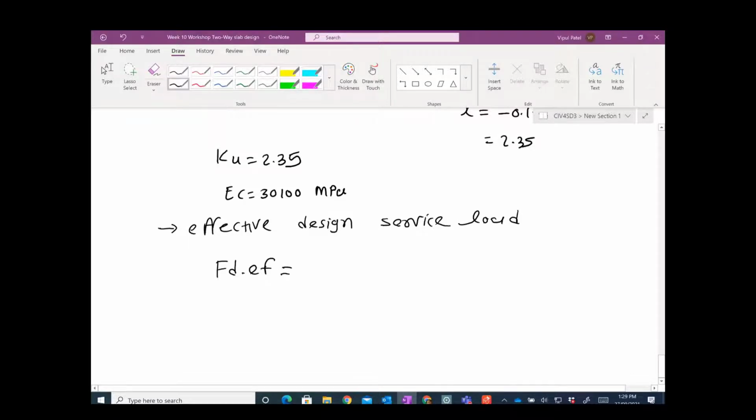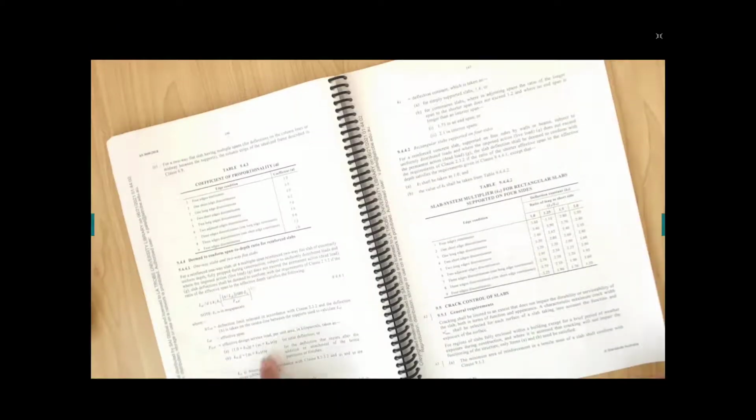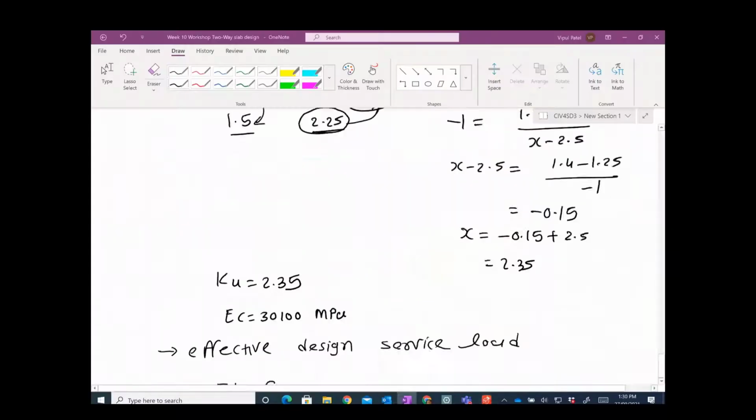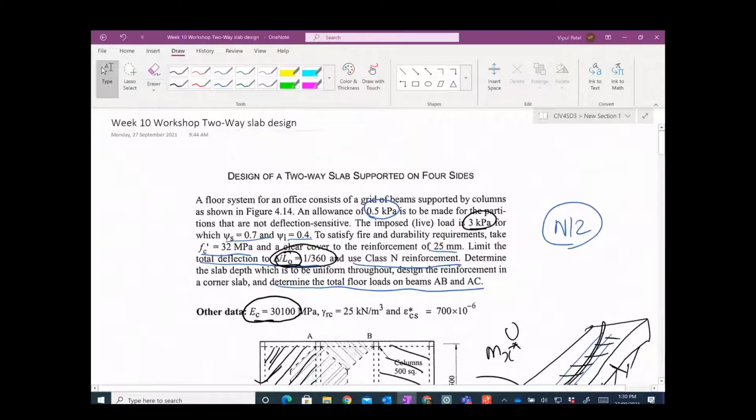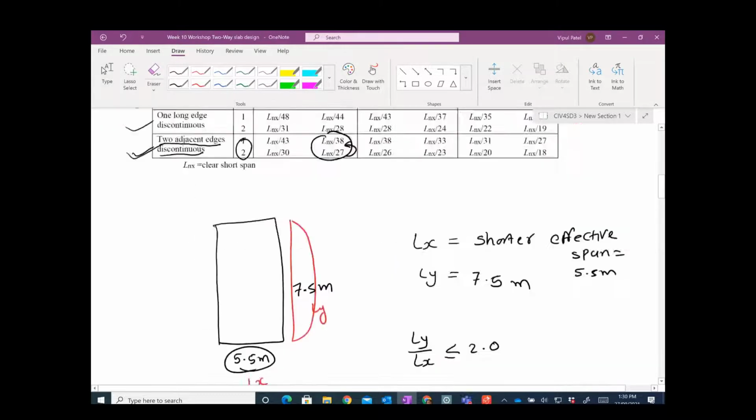Now we have two different equations. You remember that last time we used the equation with k_cs and psi_s, case 1, for deflection that occurs after the addition or attachment of the brittle finish. I think we are just working with total deflections. So in that case we will have total deflections. We have the column that says the deflection limit is on the total deflection. Here you go, they are saying that you need to use the total deflections. That is given here, total deflections.